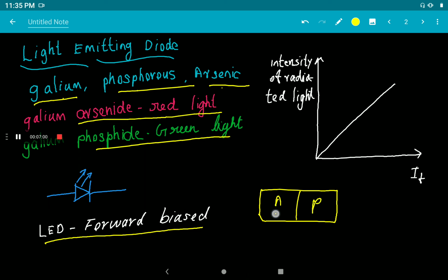Okay, so there will be more electrons in the N region. N-type material electrons will start to flow into P-type material when it becomes forward biased. We know that the free electrons are at the conduction band. The electrons are free from the nucleus, so they reach the conduction band, so they have a higher energy level